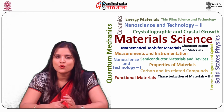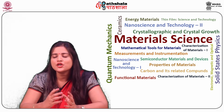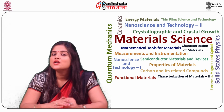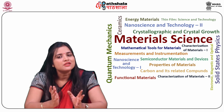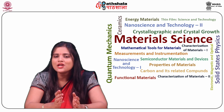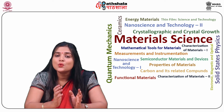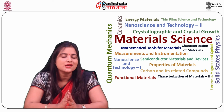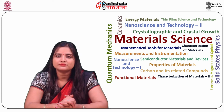The gain of an op-amp can be controlled by introducing a modification in the circuit which involves the use of feedback. That is, the output signal is fed back to the input either directly or via another network. This is known as closed loop configuration. For most practical applications, the op-amp is operated in closed loop configuration.